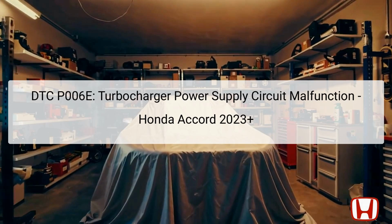The DTC, or Diagnostic Trouble Code P006E, indicates a malfunction in the turbocharger power supply circuit for the Honda Accord model year 2023 and onwards. This specific error occurs when the voltage of the power supply circuit for the turbocharger wastegate control actuator drops below a specified level. The PCM, or Powertrain Control Module, detects this abnormality and stores the code as a signal for